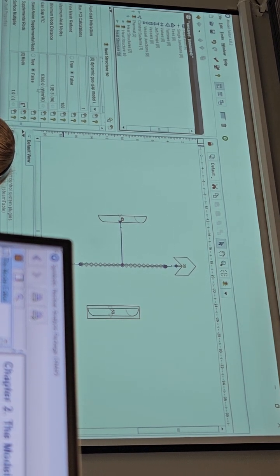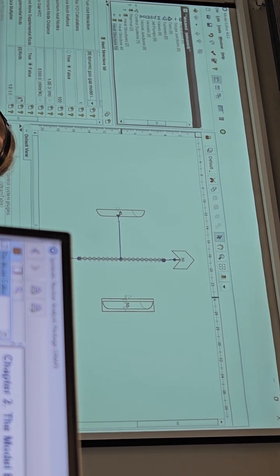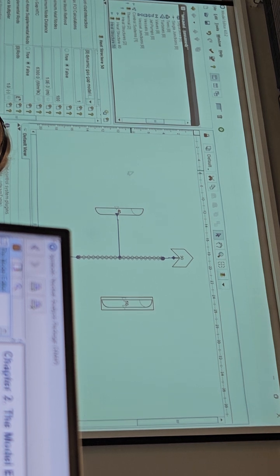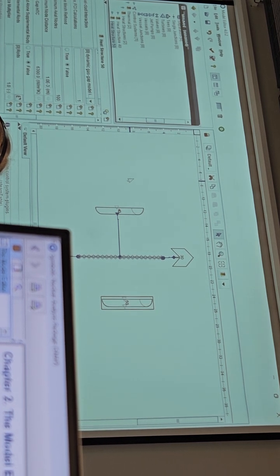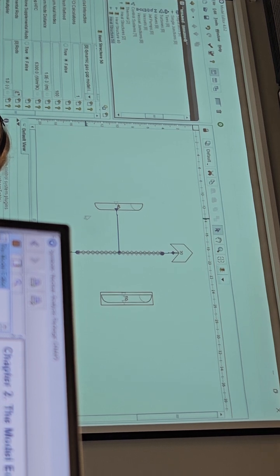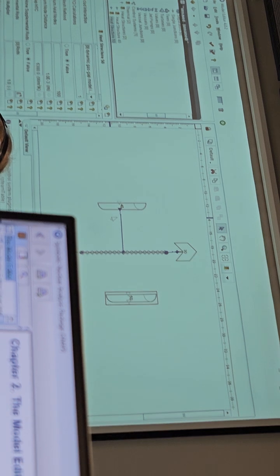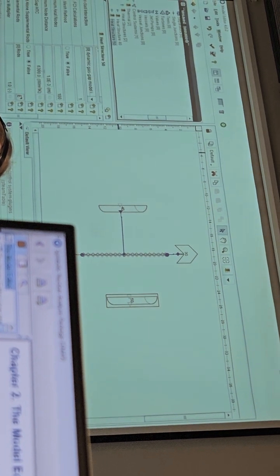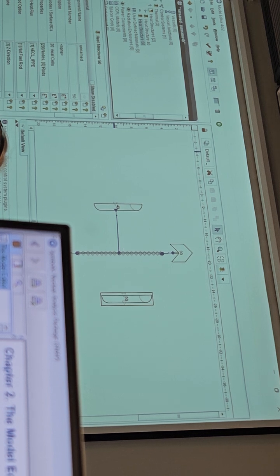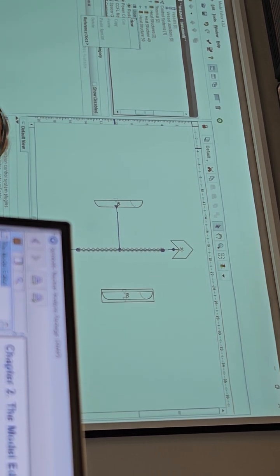The material is the same. No, we will modify the material. We need a common and basic database. We don't have glass. Yeah, we will have to create a new material manually. So we just need to go on the left side to the thermal and use the defined materials.